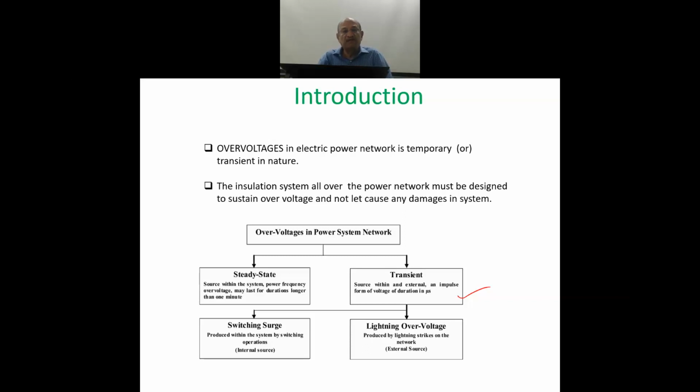And every switching operation may result in a switching surge, that means switching overvoltage. That switching overvoltage could be of different magnitudes, like the lightning overvoltage, which depends upon the magnitude of the current injected by lightning.